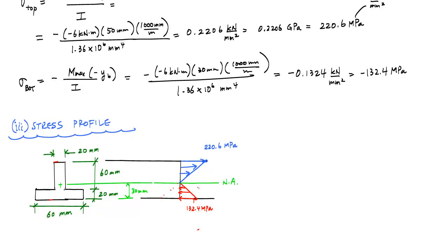This is my stress profile. Now the stress profile is not a 2D thing. This whole thing is actually extruded over the surface of the cross section here. So this portion of my area would have this trianguloid-ish kind of deal, and then this portion of my cross section would be in compression, would have a T-shaped trianguloid, I guess is the way to describe it.